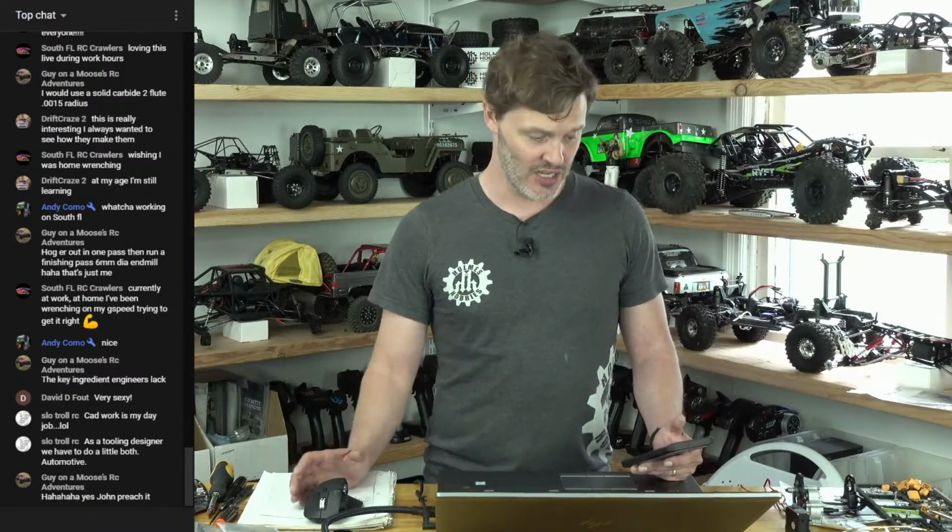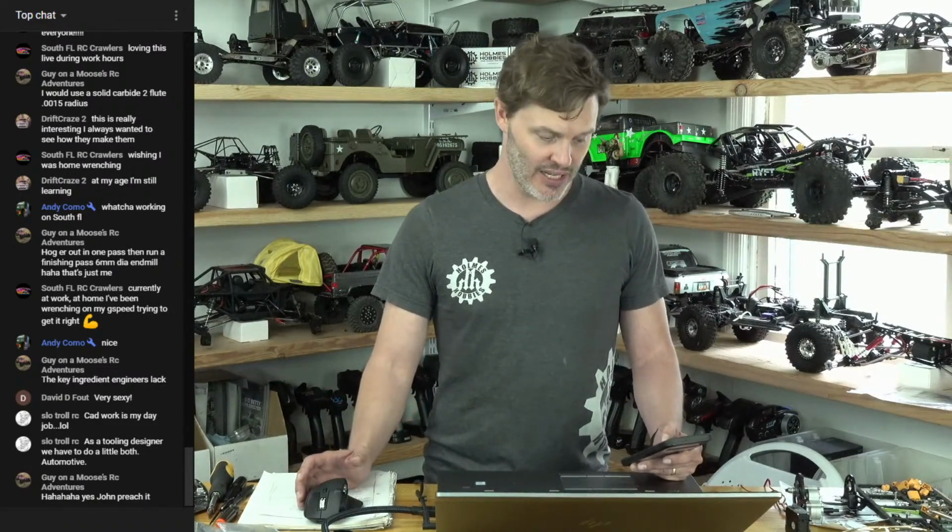Now they do run warmer because it's a smaller motor. There's less ability to dissipate heat. However, the torque production and the resistance, if we're comparing kV to kV, is going to be better on the L version. Now, is that going to be plenty in Rift? Yeah. Honestly, 2100 kV either way. So if you want to get that XL version, then get the XL version, because I know we do have them, and it will work just fine, and it will run cooler than your 1415 from Castle.